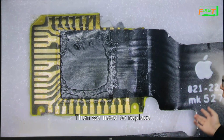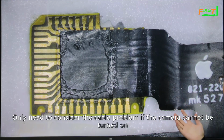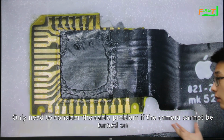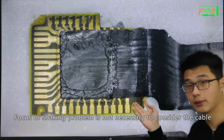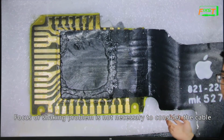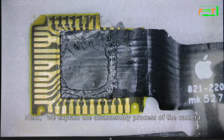Then we need to replace. Only need to consider the cable problem if the camera cannot be turned on. Focus or shaking problems do not require considering the cable. Next, we explain the disassembly process of the camera.